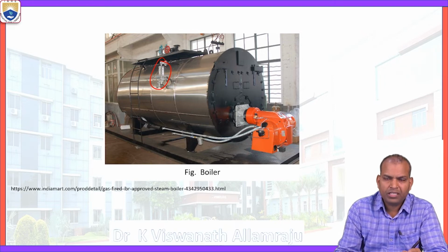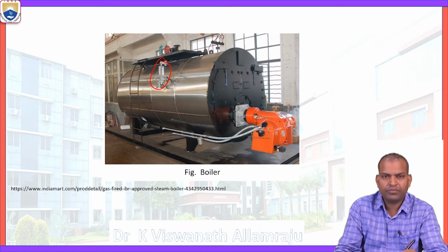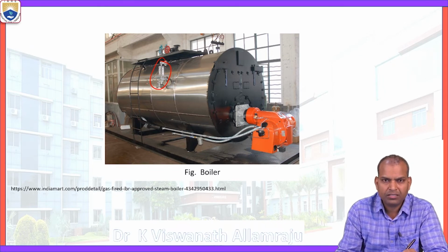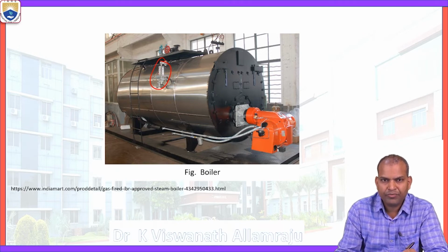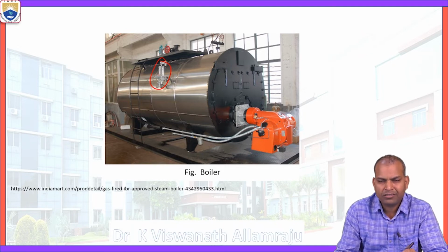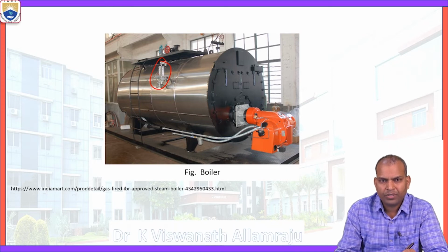These various parts are attached to a thin cylinder because the pressure gauge indicates the level of the pressure inside the cylinder. And when the pressure exceeds the factor of safety of the cylinder, the safety valve opens, giving a pathway to release the gases or the fluid inside the cylinder in order to prevent the blasting of the cylinder.